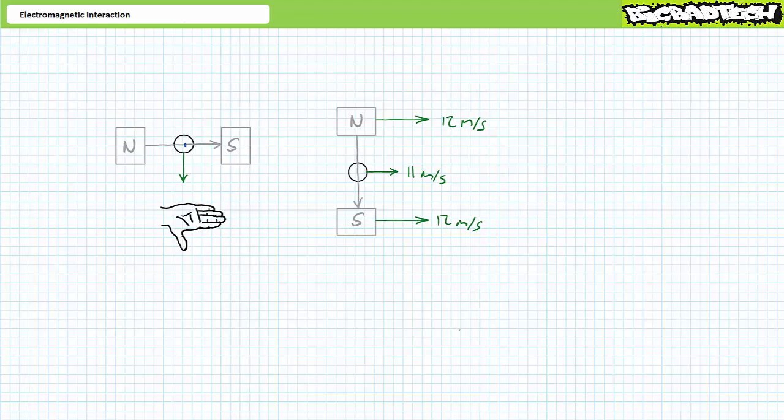Orient the thumb such that it points downwards in the direction of movement. Unless you've got a weird shaped right hand, your right palm should be facing you. This implies that voltage will be induced such that conventional current will flow out of the screen. The second scenario is admittedly a little odd.